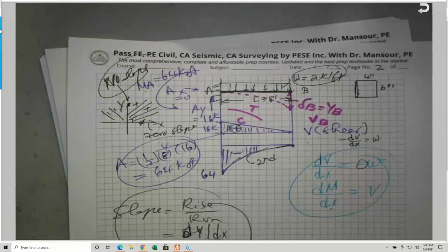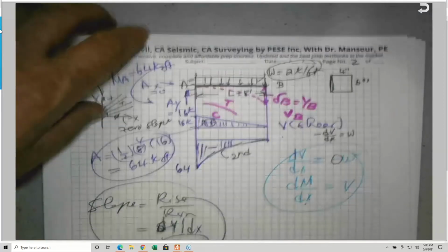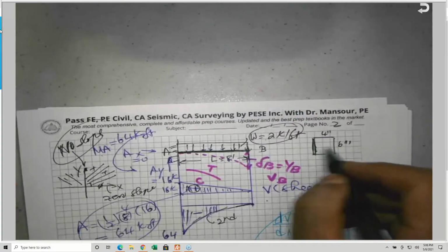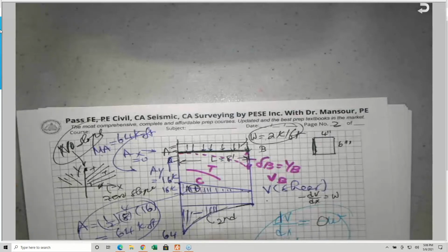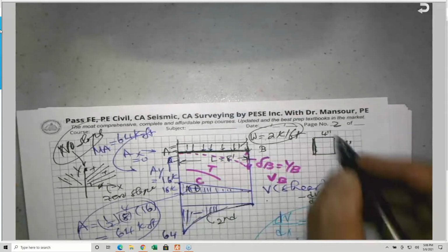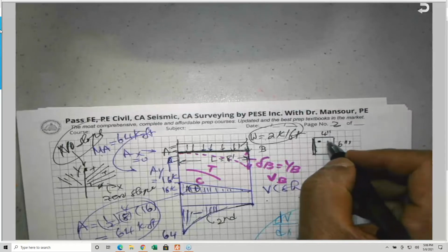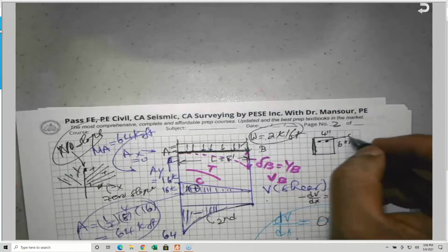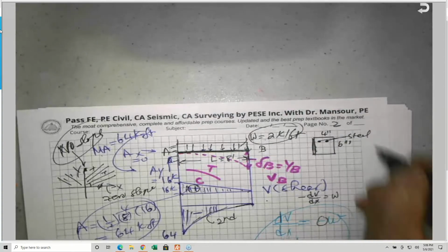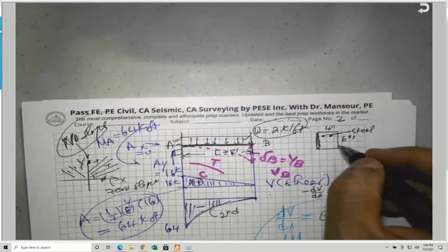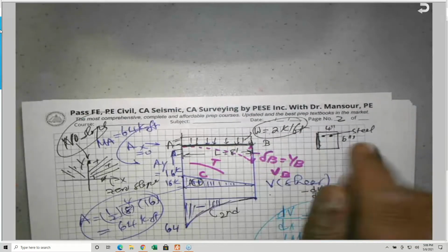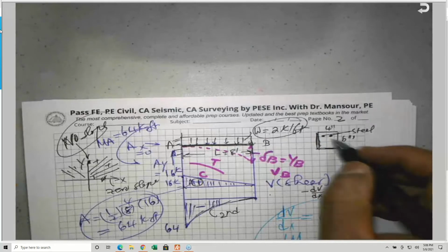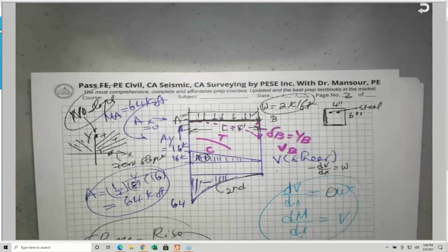and the positive and negative bending moment, because later on we are going to look to the design for concrete. For example, let's assume this section, which is a very small section, but let's assume that this section is made of concrete. So the tension at the top and compression at the bottom, where should I put the rebars? We put the rebars along the tension side. So these are the rebars, the steel rebars. Okay, it should be along the tension side because concrete is very strong in compression, which is the bottom side, below the neutral axis, and it is very weak in tension. So this is why we put the rebars.